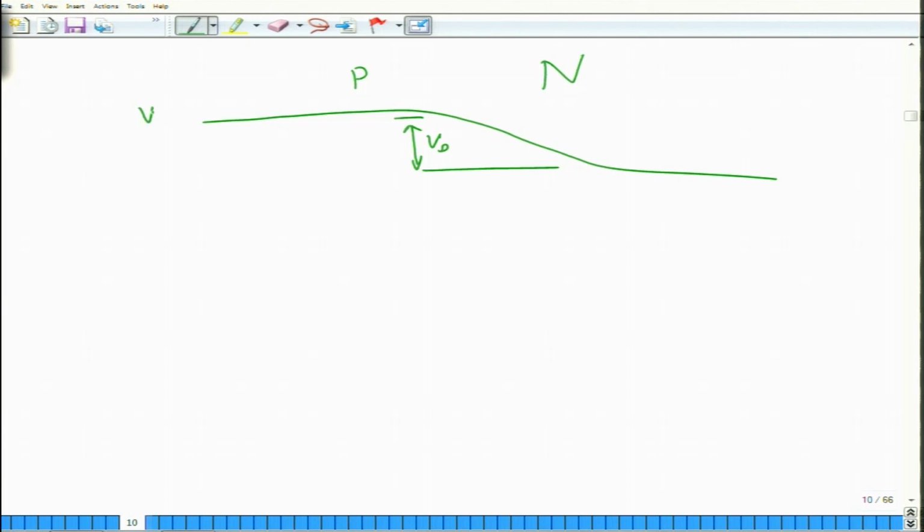So, the vacuum level actually undergoes change, but it is a continuous change. So, the levels continuously change from the small p region to the capital P region. However, that is not so the case for the conduction band, because in the conduction band case, initially it will go like this. If it was a small n, it would have continued and dropped, right, but this is not a small n, this is a capital N. So, it can't continue forever, but it does go down and then goes back up. It will never reach the level beyond here.